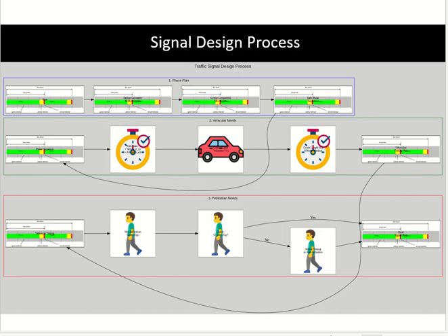Okay. And there can be multiple lanes for one movement. So I don't have to design for the whole movement, I have to design for one lane. Because the other lane is together, right? So if there are 3 lanes, I have to decide which lane I am designing for. And for that lane, I will need the volume.